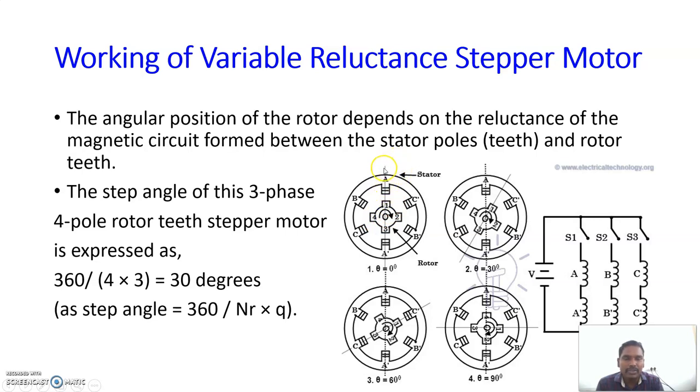Now we are giving a pulse to the stator coil. This pulse may be a positive pulse or a negative pulse. If you take it as a positive pulse, this A part will be fixed as a north pole, and one portion of your rotor will also be a north pole. During that pulse, both north poles repel each other, so that your rotor shaft is moved from this position to this position due to this repulsion principle. Now the second position is reached at about 30 degrees.